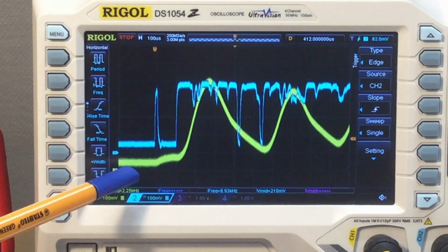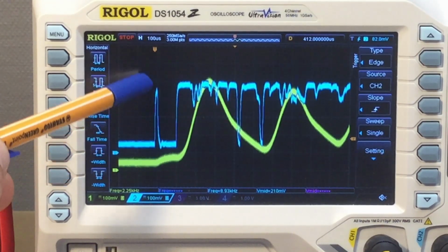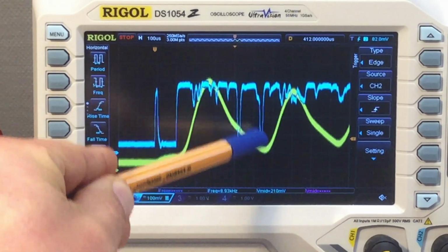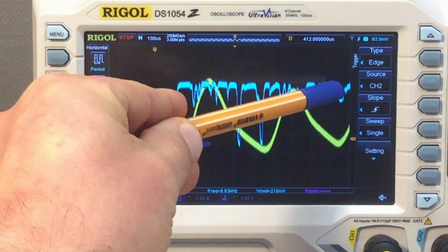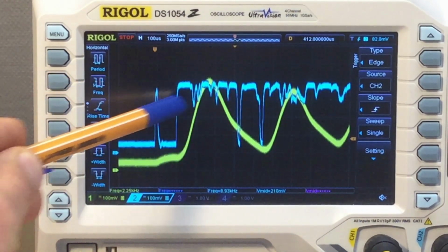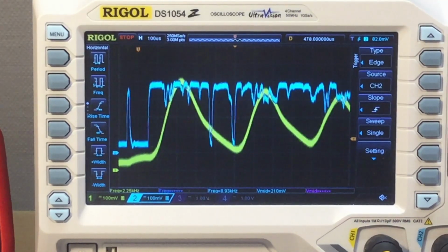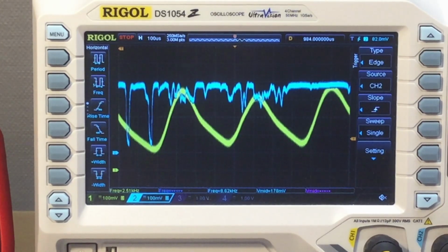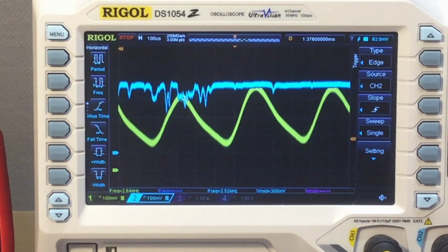So here we are in the steady state, that was a lower current range, and then I actuated the switch, and you see what's coming out of that switch. The input through a resistor network, the input signal to our positive input of the op amp. It's a mess. It's a complete mess. And yeah, we can scroll through here, and it takes a whole lot of time until that signal is stable again.